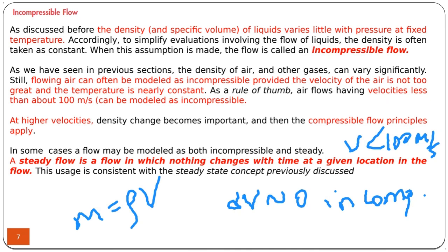For the case of the car, is it compressible or incompressible? Incompressible. Why? 100 meters per second is a really high speed. Yeah, it's 360 kilometers per hour. So normally, if it's not a racing car, it's an incompressible flow. How about the flow around an aircraft? It most likely will be compressible. Yeah, most likely it's compressible, meaning that at those speeds, the air in front of the